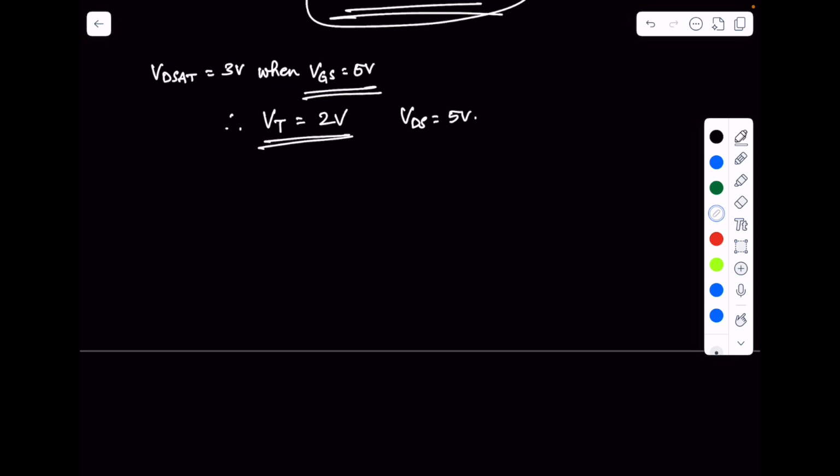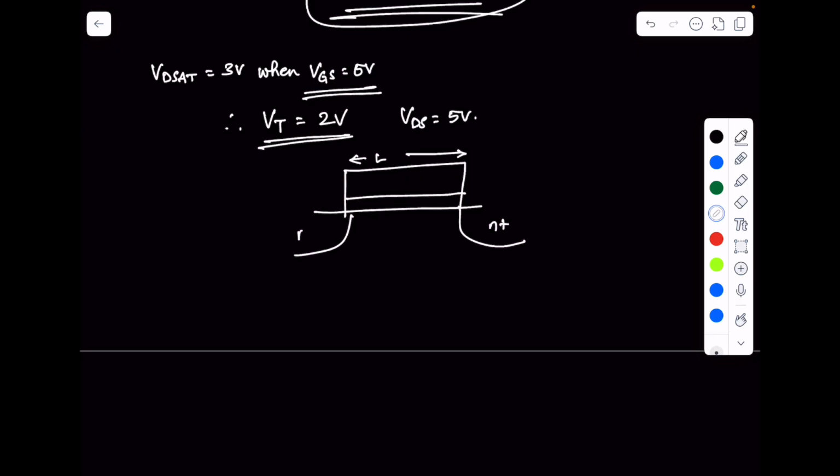So in other words, if you think about the saturation, if this is your gate length L, this is your N plus, that's your N plus, P substrate, bias. If you look at the depletion region, it's not only pinched off, you also see it creep in to the device. Now, obviously, in this case, you don't see a GDS. In other words, you don't see ID increasing. So you can assume that this delta L is much, much smaller than L, but you see that this pinch-off point is going to move in slightly.